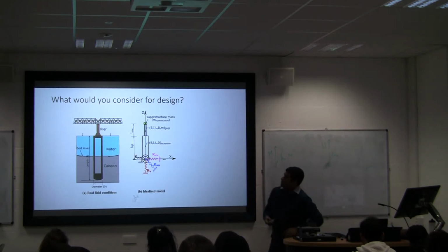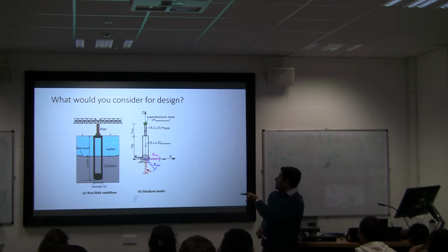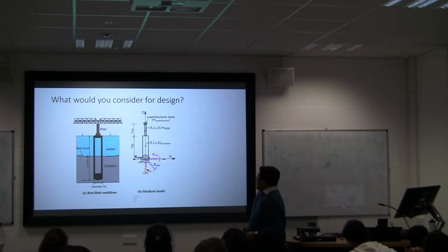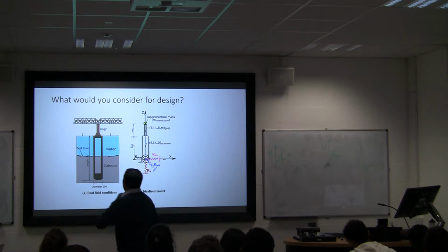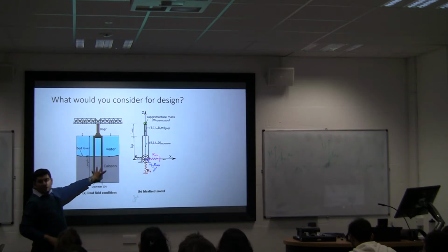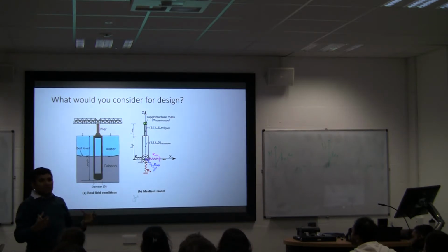So, exactly what we discussed just before. One of the important parts of a bridge is the dynamics, right? If you choose a particular foundation, you can find out the stiffness. A smaller pile or a smaller caisson will have a small stiffness.